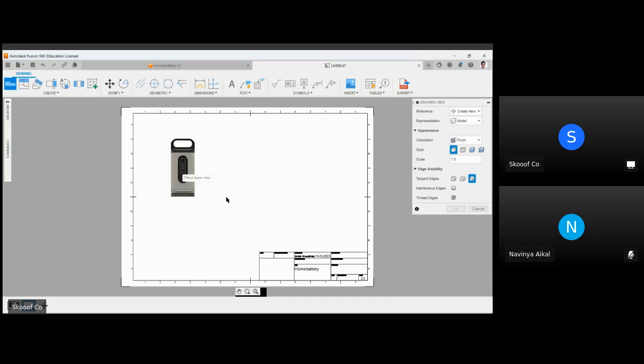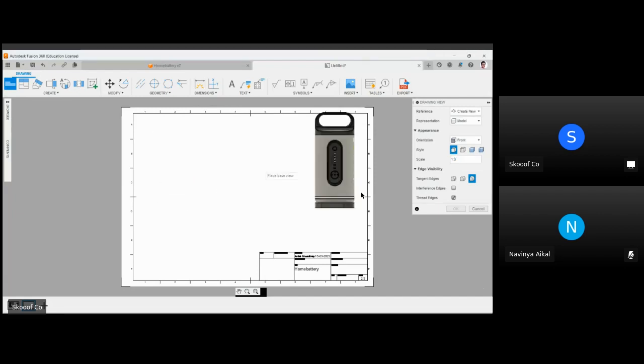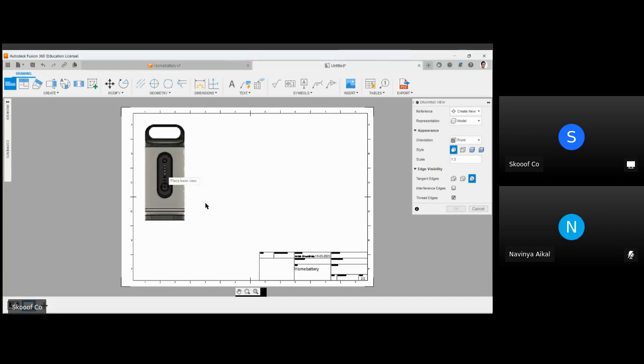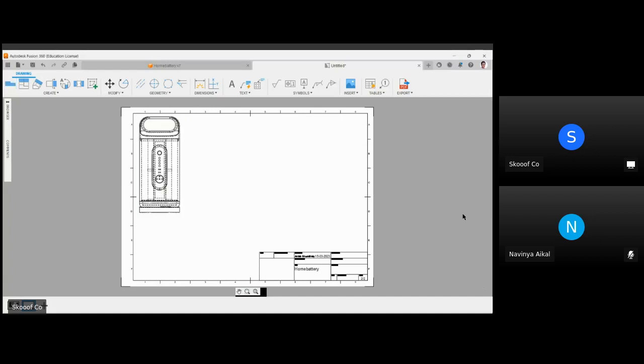So you get a basic view of the product. So let's go for 1:3 as it was our view here. Click on this one. As we are giving different types of view, we'll try to keep it consistent and filled inside the form. So we'll click on this one. We will do the visible and hidden edges as well, and we will shorten it out, which will show the interference edges. And okay, our model has been generated.